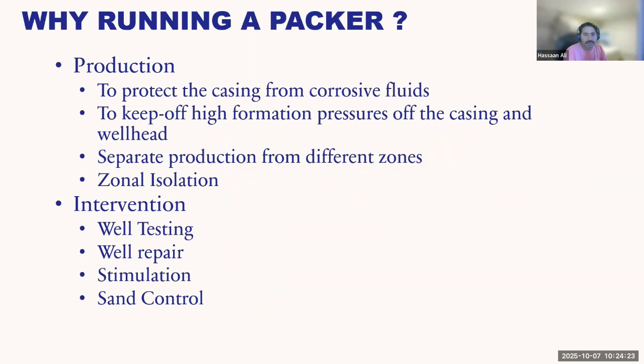So why do we need to run a packer? There are two factors that influence the running of the packer: production and intervention. From the production side, you want to run a packer to protect the casing, primarily from the corrosive fluid, and to keep the high formation pressure off the casing and the wellhead. You also want to use packer as a means to separate production from different zones and also for zonal isolation. From the intervention point of view, you want packer so that you can test your well, repair your well, do well stimulation, and control sands.